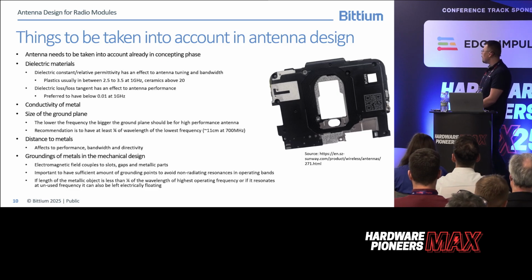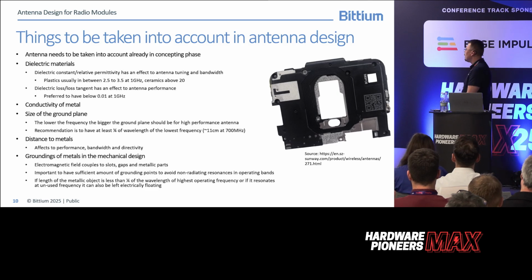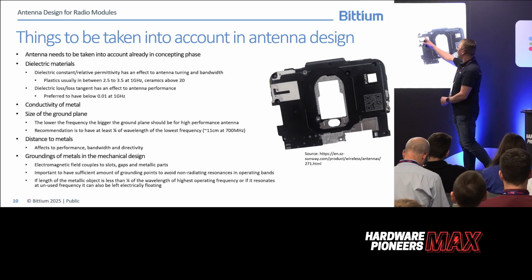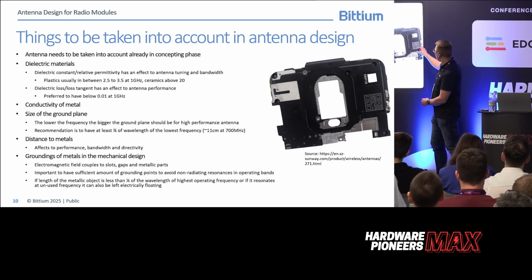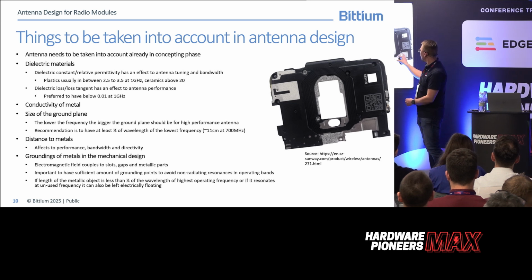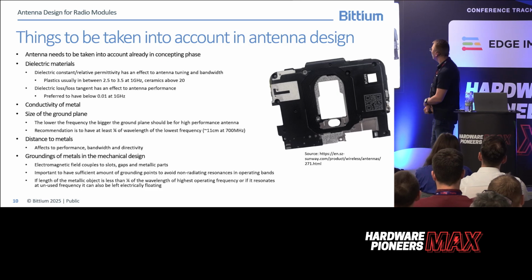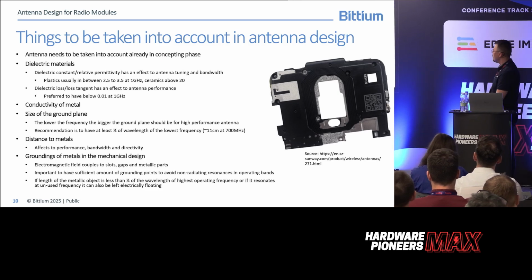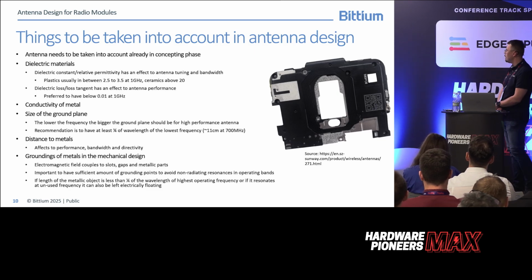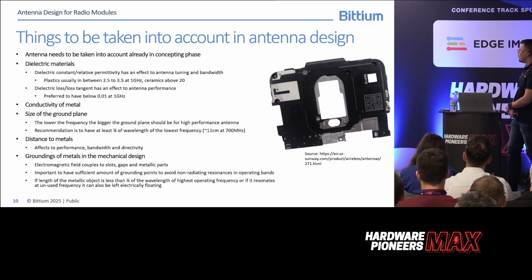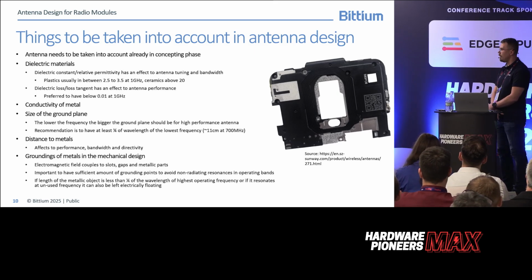So here we have a picture of one mobile phone antenna. We have some antenna traces here, then an NFC antenna there, then there's some supportive metal there, and some grounding gasket there. These grounding gaskets are there for a purpose, to prevent non-radiating resonances from some parts of the device's structure.